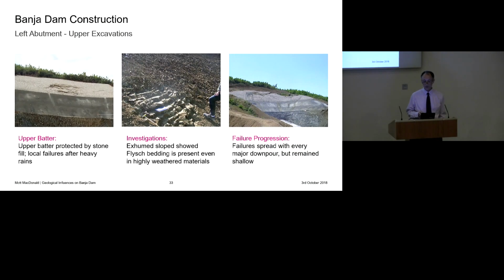So looking at those upper excavations first, the detail was to excavate the slope and cover it with a layer of crushed stone, which was supposed to hold the water back and allow it to pass over the rock and end up on one of the berm drainage system. We were a bit sceptical about this design detail, and it wasn't very long before our fears were realised, and we had minor failures like this occurring in the batters.